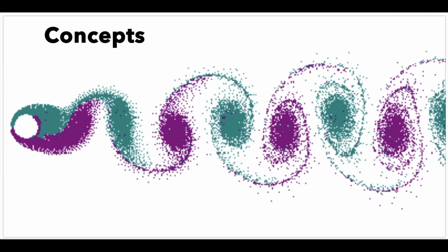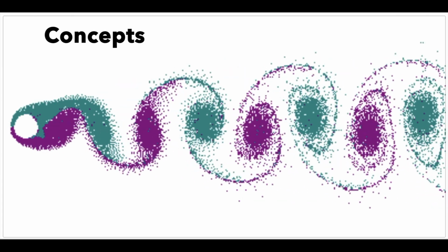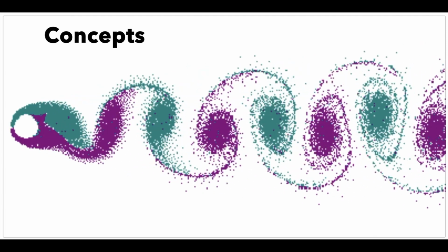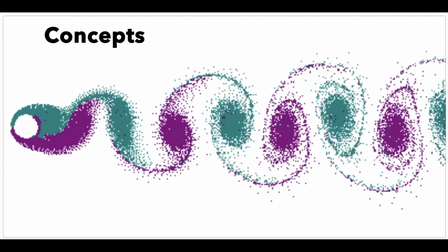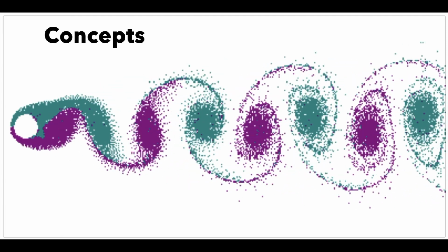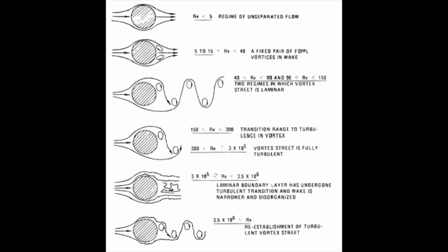In fluid dynamics, vortex shedding is an effect that occurs when flow becomes turbulent and oscillates behind an object. Flow on both sides of the object periodically detach at different rates, creating a snapping effect that is easily seen in videos of flow over a cylinder. Similar to other types of turbulence in airflow, this flow pattern will take energy out of the fluid and create substantial amounts of drag. This shedding also has the potential to match the natural frequency of an object such that the object can become damaged or dislodged.